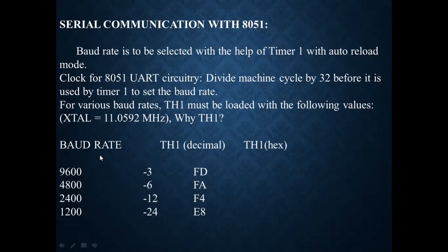Timer 1 mode 2, sir, because we are using timer 1 mode 2. So in mode 2 we need not load any value to TL, the timer low, because it is automatically loaded from TH1.